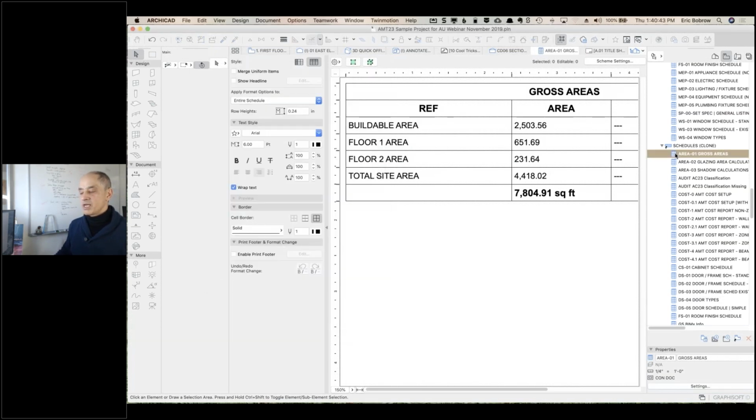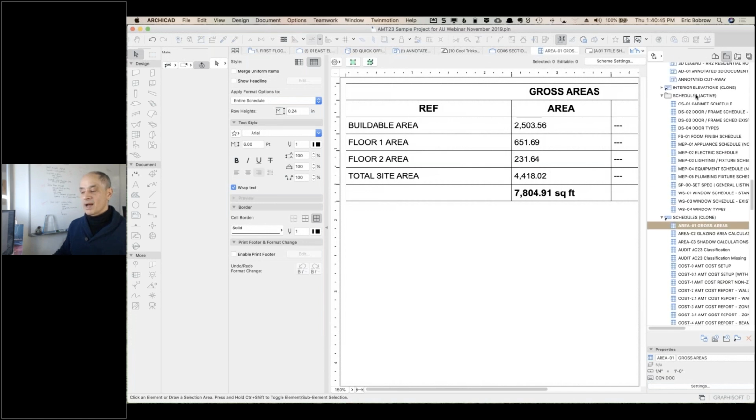Walls are visible, all the equipment, etc., are visible here. In any event, this particular one, if I wanted to have it in my active view because it is one of the ones I'm referring to and working with, you literally can just drag this into the schedule here or put it wherever you want, let go. It did not leave the clone folder because the clone folder by definition always shows every viewpoint in the folder that you're referring to, in this case, the element schedules. But by dragging it in here, it's created an equally good view for that.